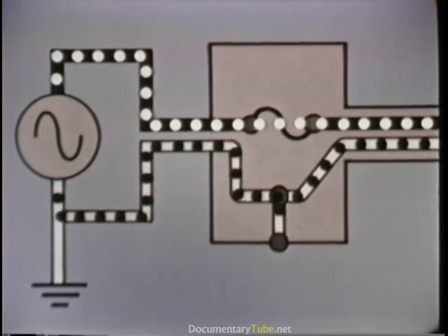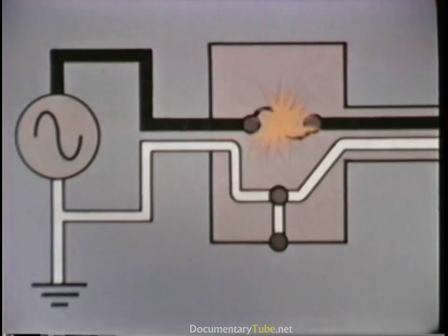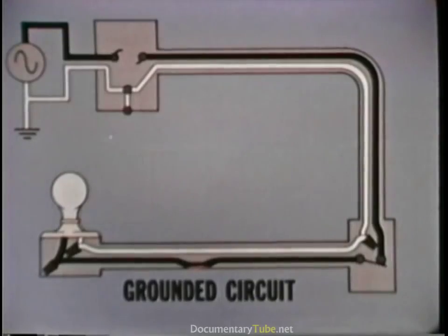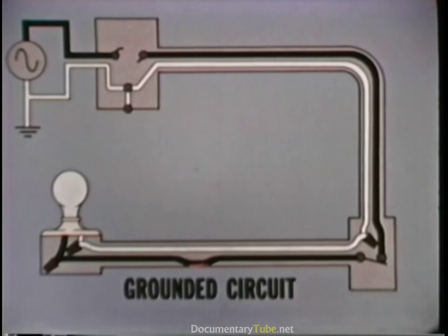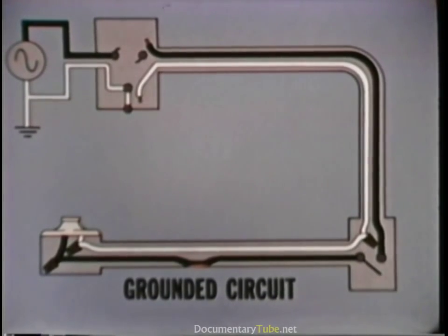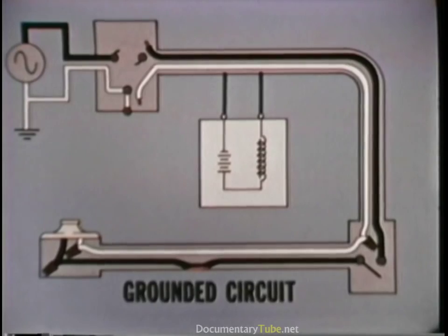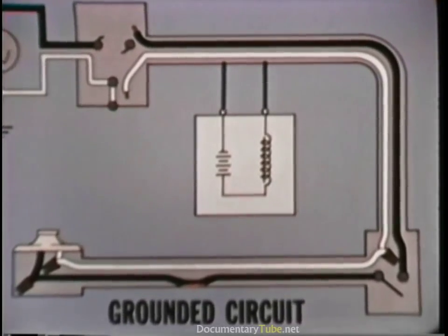This time, let's examine another case where we come on the trouble site to find a blown fuse. Once again, to deal with the circuit safely, remove the wires from the power source. Remove the other elements in the circuit by opening the switch and removing the bulb. This time, instead of using a multimeter, let's use a buzzer-type continuity tester.